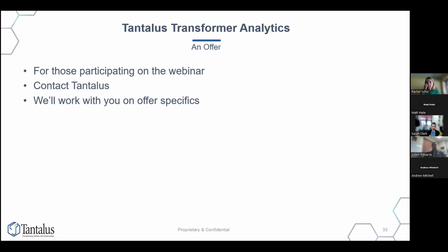And in parallel, you'll set up your transformers with the circuits and feeders they're on, and the analytics ties them all together. And the audit will flag, hey, you said this service that's tied to this transformer is over here, but the other chunk of data that you sent in says that it's on this feeder over on the other side of the system.